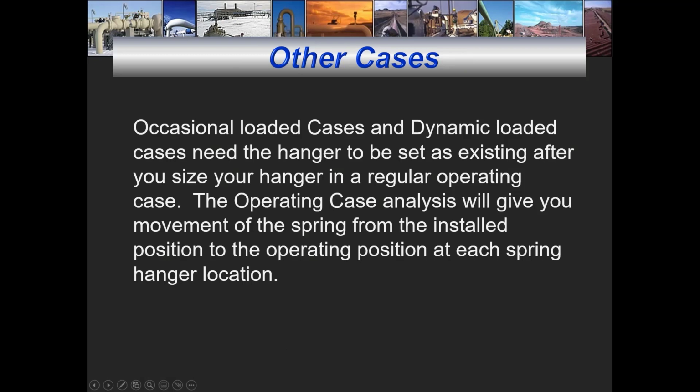Other cases, like occasional loaded cases and dynamic loaded cases, need the spring hanger to be set as existing, not sizing, but as existing before you run the calculations on those.